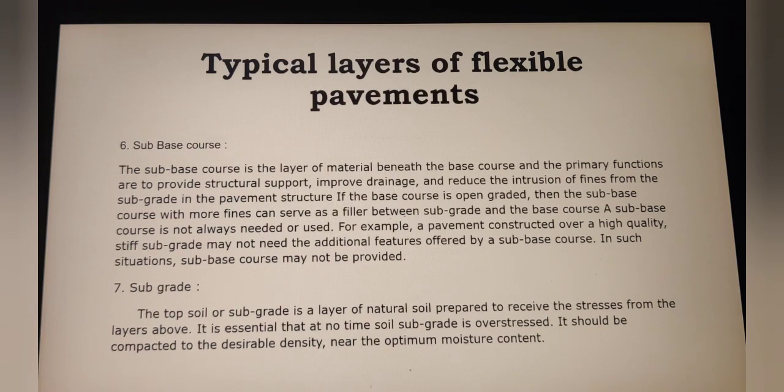So a sub-base course is not always needed or used. For example, if a pavement is constructed over a high quality stiff subgrade, then in that case the sub-base course is an additional feature offered which is not required. So in such cases you can avoid the sub-base course.